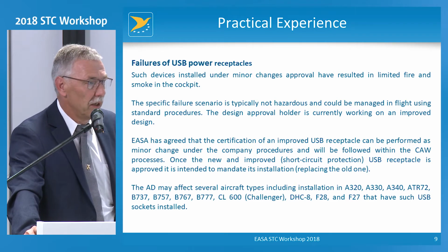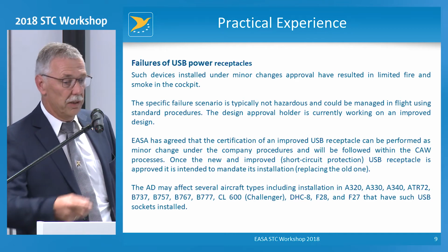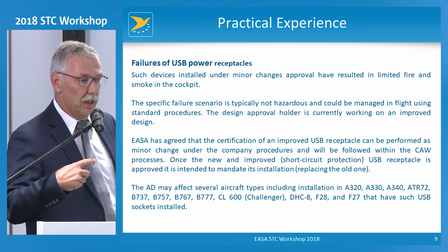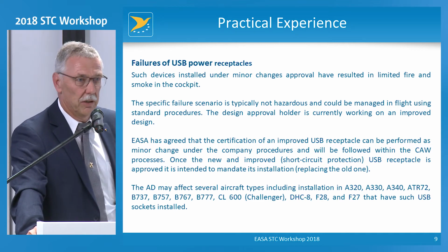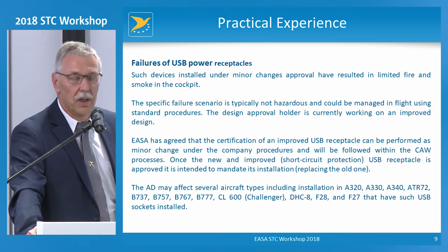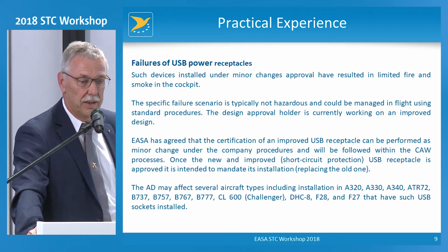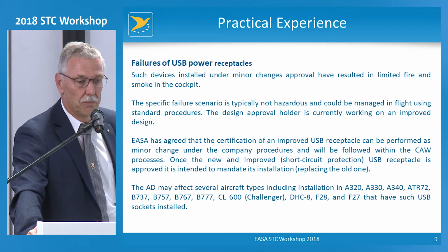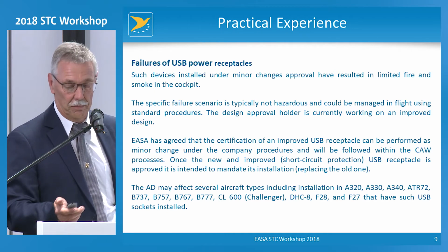The approval holder is working on improvements, and EASA has agreed that even the improved modification can be carried out as a minor change. However, finally it will probably result in an AD that affects several aircraft types where such USB devices are installed.